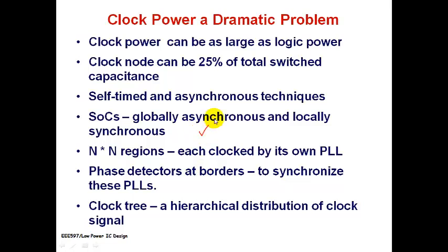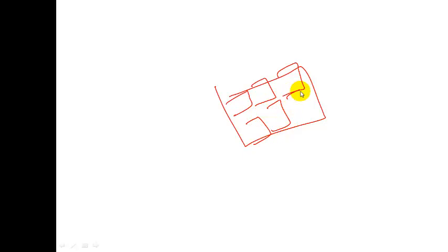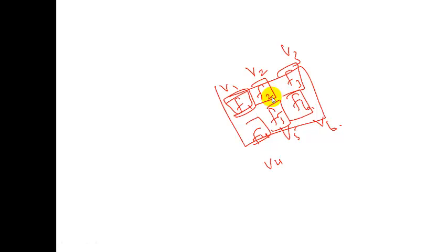And there is another such option also. Each chip would now be having different regions, first region, second region, third region, fourth region. Each of these would be operating at F1, F2, F3. I hope you remember we have discussed sometime about different frequency and different voltage ranges also. I could have this operating at V4, V5, V6. So the first unit would be operating at V1, F1, V2, F2, V3, F3. So you will have multi-voltage operation and multi-frequency also.